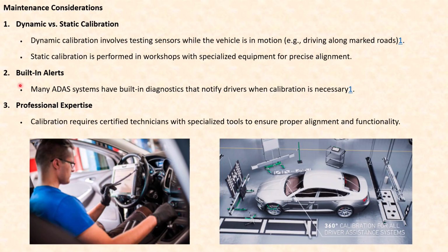Now, there are also built-in or plug-in alerts. Many ADAS systems have built-in diagnostics that notify when calibration is necessary. So if there is some disruption or misalignment, there is an onboard diagnostic. There are ADAS diagnostics which notify the driver that such and such an ADAS sensor needs to be calibrated. Next comes professional expertise.